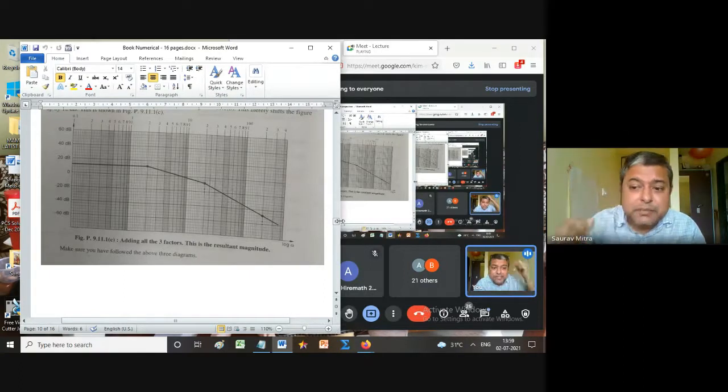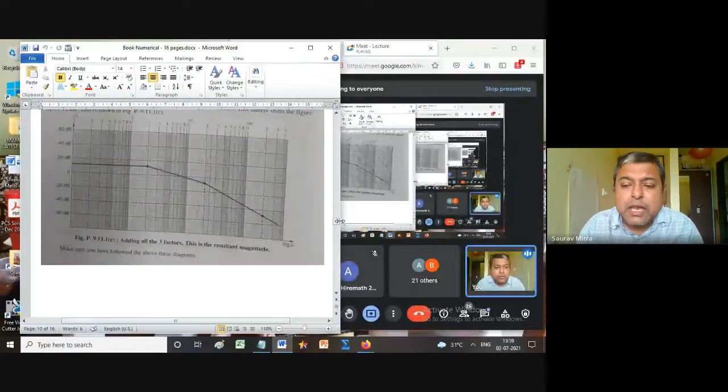So what is 8 radian per second called? It is called as omega GC, gain crossover frequency. लिख के रखो. And we are finding, at omega GC 8 radian per second, the phase is tan inverse omega by 2 minus tan inverse, equal to minus 98 degree.